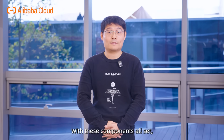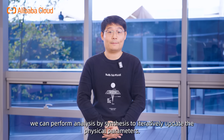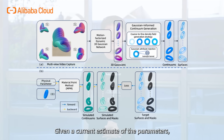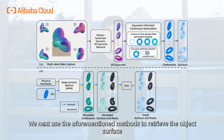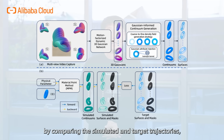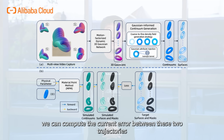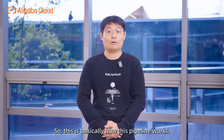With these components all set, we can perform analysis by synthesis to iteratively update the physical parameters. Given a current estimate of the parameters, we perform simulation and generate a simulated trajectory. We next use the aforementioned methods to retrieve the object surface and use Gaussian splatting to render 2D masks from various viewpoints. Finally, by comparing the simulated and targeted trajectories, we can compute the current error between these two trajectories and backpropagate the error to update the parameters accordingly. So this is basically how this pipeline works.